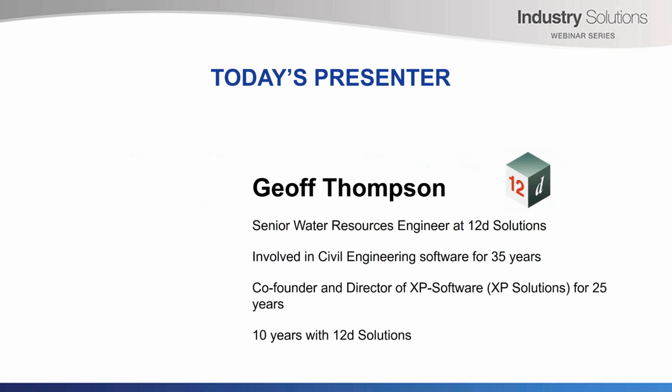This webinar will provide an introduction to Dynamic Water Supply, a new module in 12D Model 12. This module completes the trilogy for three waters: stormwater, wastewater, and water supply, and allows hydraulic analysis and analysis of water quality behaviour of pressurised pipe networks consisting of, for example, pipes, junctions, pumps, valves, storage tanks, and reservoirs. It can perform static analysis, but this demonstration will mostly focus on dynamic analysis.